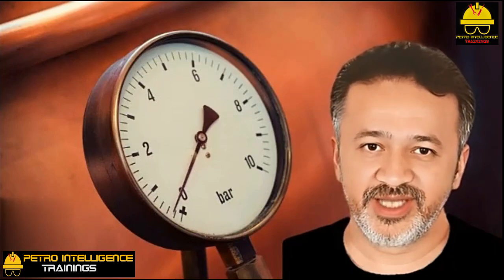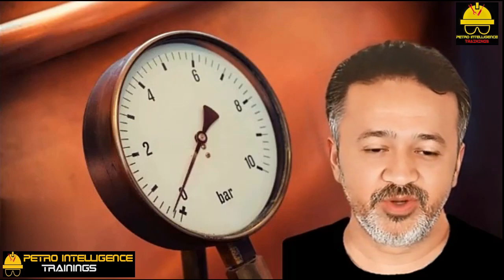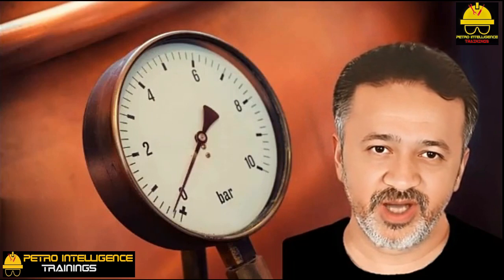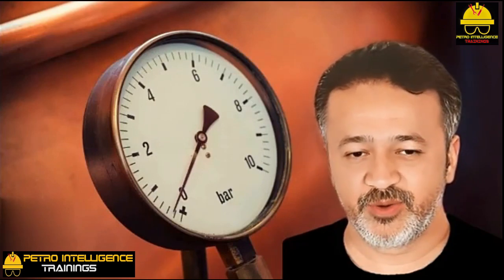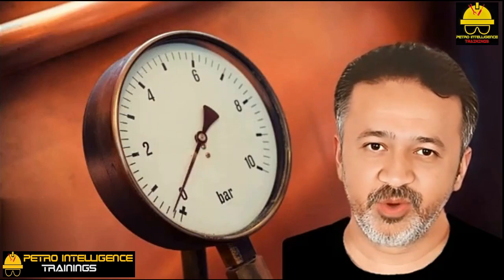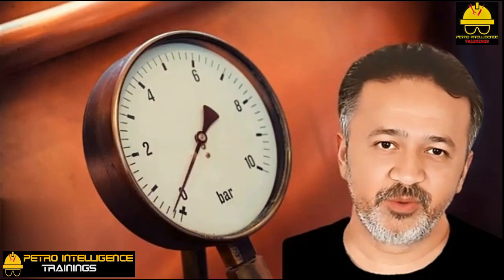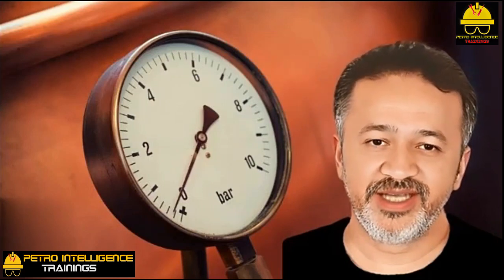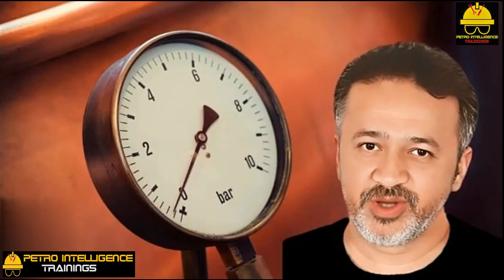Naturally, just like level indicators, the flow orifice taps can plug. If the upstream tap plugs, the flow will read low or zero. It is best to blow the tap back with glycol, but that is not always practical. If you blow the taps out with the pressure of the process stream, you do not need to refill the impulse lines with glycol to get a correct flow reading. But the lines have to be totally refilled with the same fluid.